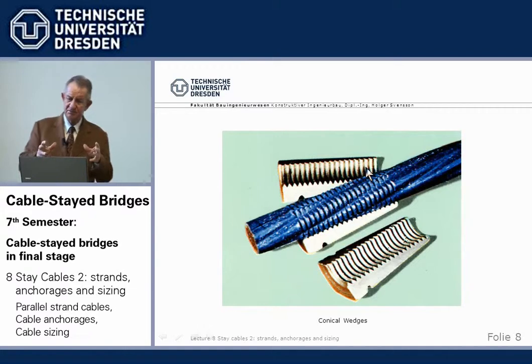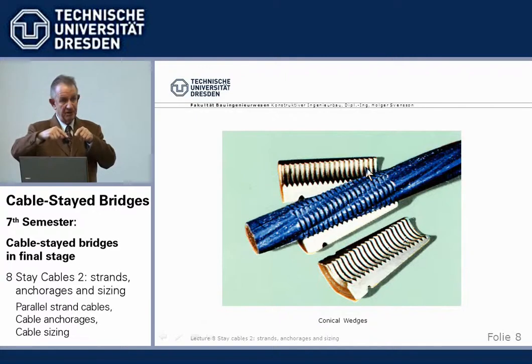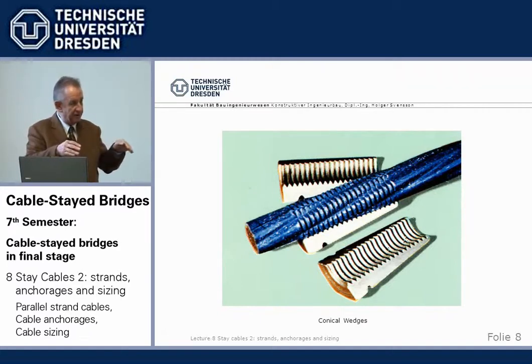if you start with a wedge with a regular tooth pattern, same teeth at the beginning and at the end, and you make a fatigue test, it breaks rather early. Why? Because the force goes, most of it, into the first 1, 2, 3 teeth, because they bite, and there's very little force transition in the end. So the length of the wedges is not active, but everything happens in the beginning. And that sudden change of stress means little fatigue.